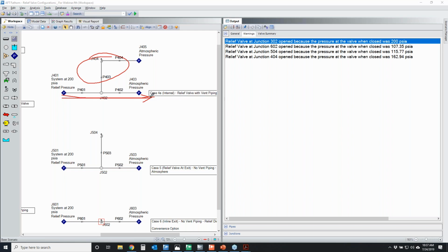So when this flow is going through my pipeline here, the pressure at this point is actually 163 psi. So I've lost about 38 pounds of pressure in this upstream pipe by the time it gets to the point where my relief line connects. However, this value is still higher than the set point, so that's cracking open.